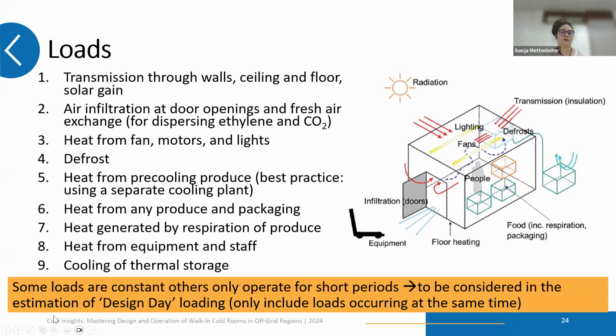Yes, so some loads are constant and others are only operating for a short period, like, for example, people going in. People are not 24/7 in the cold room. So that needs to be considered when we estimate the design day loading.